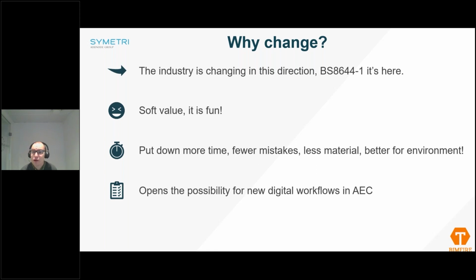We can check, for instance in a hospital, that you can't put furniture in this area. You have a space from the fire engineer. Check against any furniture. If there is any, move it away, because you can't have any loose furniture in this area because it's a part of the evacuation route. So the possibilities with these new digital workflows are endless. Basically, any kind of requirements you can think of, we can start using Solibri, Navisworks, Autodesk Construction Cloud, etc., just by having a model instead.